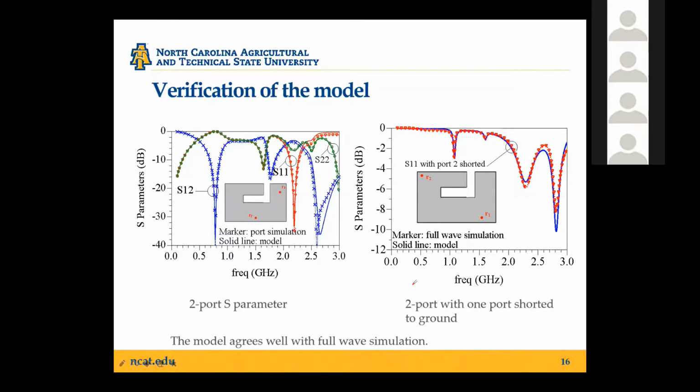So that essentially means that with the circuit model, we get a pretty accurate, highly efficient model for the entire patch antenna, and you can essentially play with whatever tricks you want. For example, if you want to design reconfigurable antennas, you can consider loading at any arbitrary locations. If you're considering designing multi-port antennas, you can test out different feed combinations.